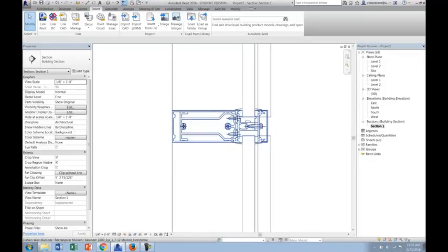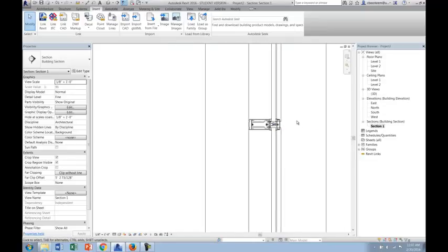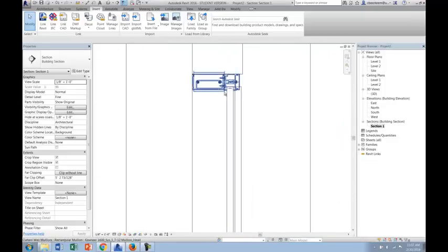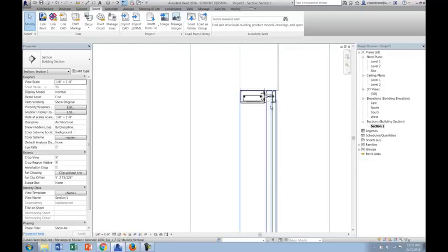And the screw type, which is actually, so this structural piece gets attached to the glazing first, and then gets screwed through to the front, and then the cap gets snapped on once this screw has been in place. So this little piece gets snapped on. So really what you're seeing here is the ability to clean up the entire thing, mostly through these kinds of small snap connections. I know those details often look quite complex, but really they're just intended to allow you to hide most of the system.